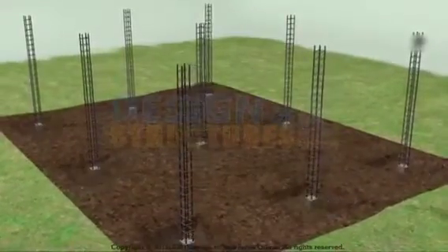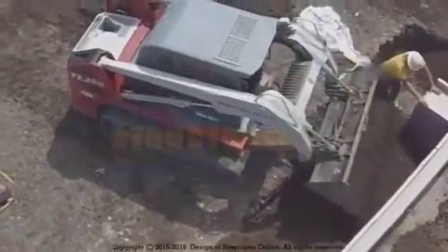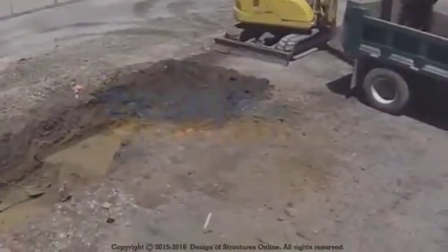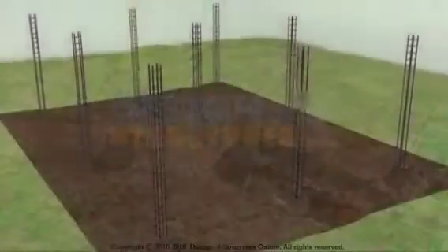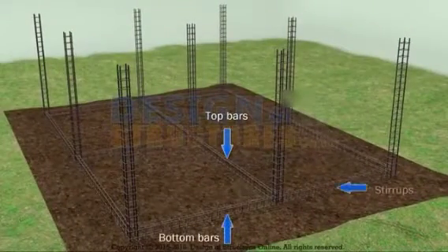Backfilling. Once the foundation is completed, backfill the remaining excavated area around the foundation with soil. Backfill provides stability to the building. Plinth beam reinforcement. Beam reinforcement shall be as per drawings. Top bars, bottom bars and stirrups to be placed with proper development length.